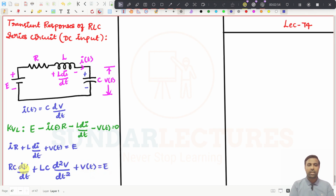See, what is this? This is nothing but a second order differential equation, with the second derivative, and the first derivative, and a constant, equal to the right hand side excitation function. And what we do is always go for a coefficient of one before the highest derivative, here the second derivative. So we have to divide by LC.